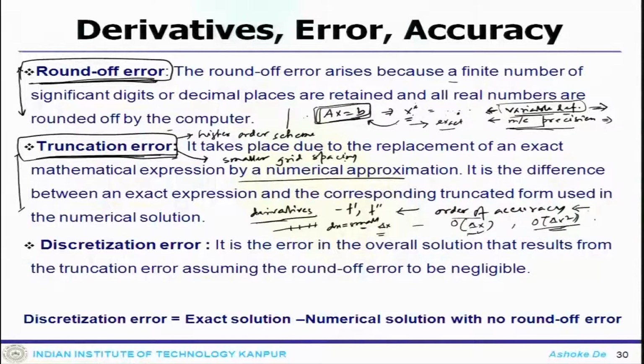That means any higher order term that you have truncated off, that would be of order delta x square or cube, they will not lead to too much truncation error. So, this is something in the user's hand, and one should handle it very carefully. When you look at any CFD code, whether it is commercial, in-house, or you develop your own code, this is one term people keep on talking about: what is the order of accuracy of your code, because that means a lot.